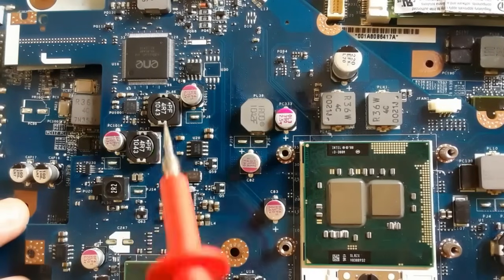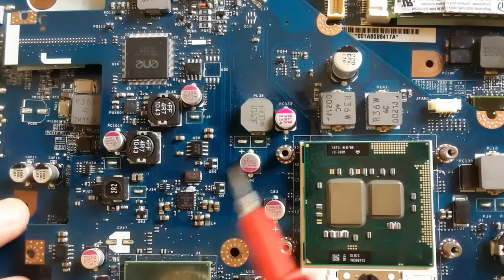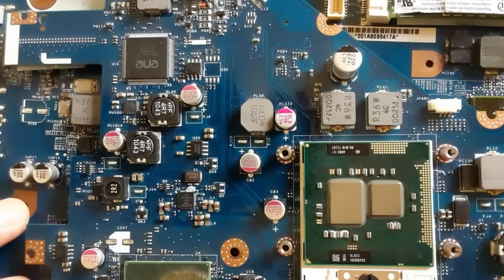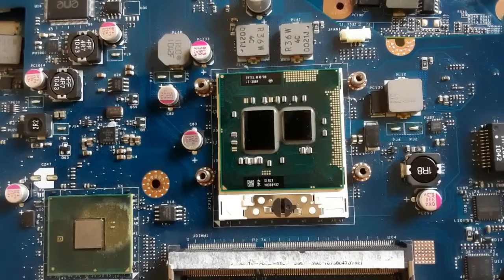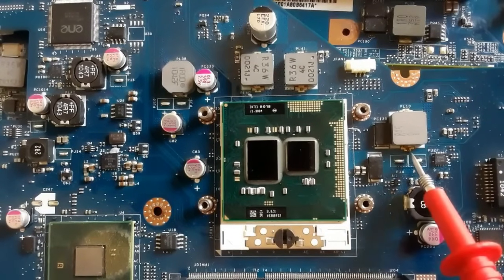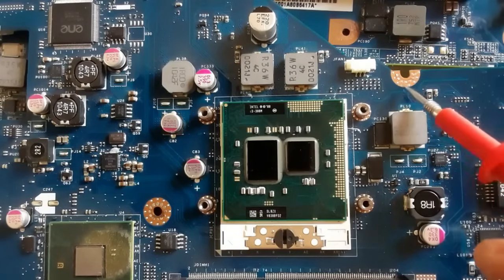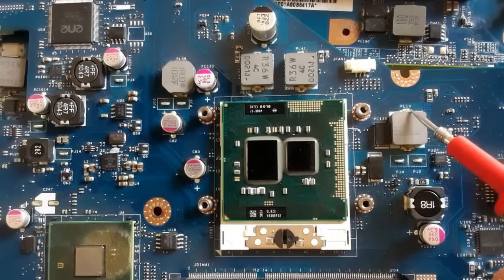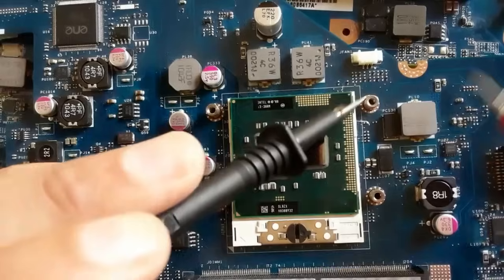Okay, so if you find any inductor that is shorted to the ground, it means there is a short circuit in that circuit that inductor belongs to. Okay, so as you can see here, we have many inductors. In each circuit you will find an inductor, capacitors, and MOSFETs. We have an inductor here, two terminals. If you check these two terminals with the ground, you should never find any short between the inductor and the ground. Always the inductor is connected to the voltage or to the power rail.